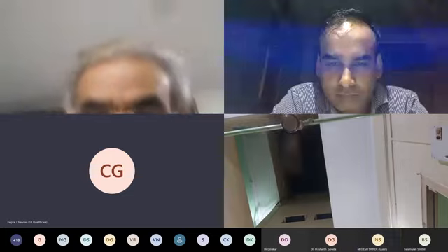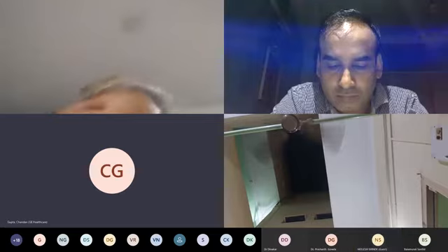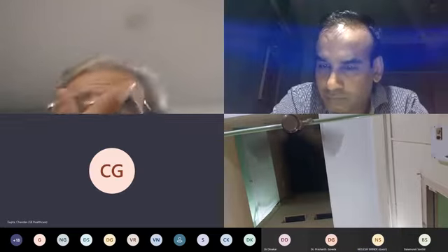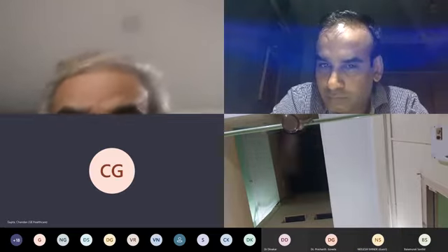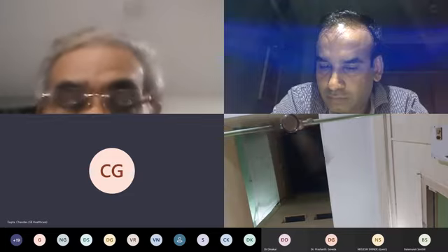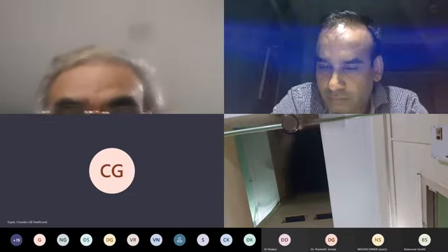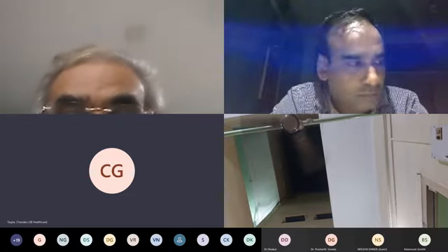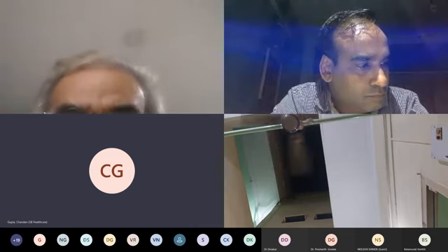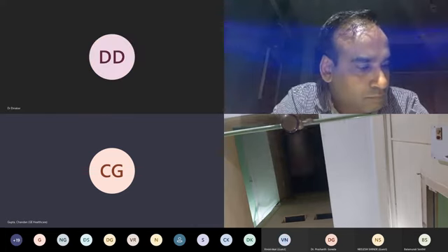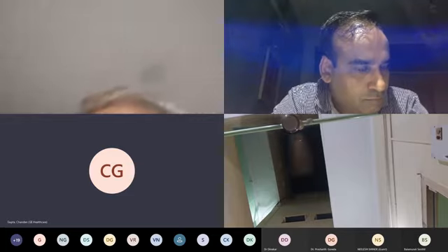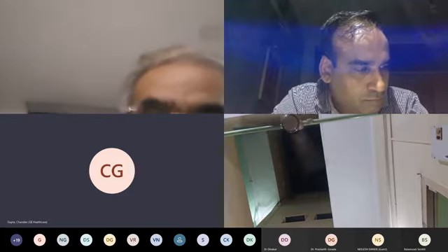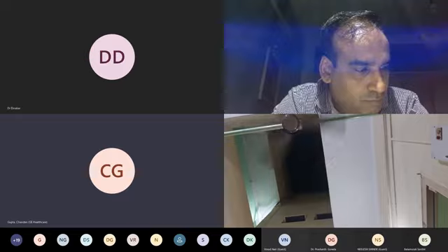I will just give an example. We talked in my presentation about how we have reduced the sound. One of the things that produces sound is the alarm speaker. In the speaker, we tried 216 positions to see where to put it. We have put it on the pedestal at a 45-degree angle to the floor, so that with the bouncing effect, everyone can hear it properly, but at the center of the bed, the noise level is the lowest. So that's the design feature.